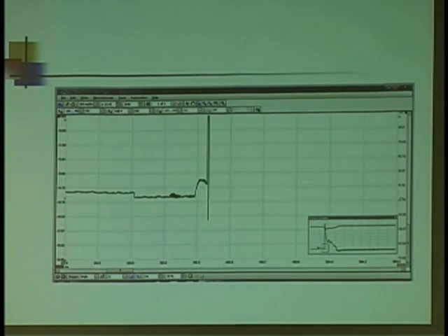When you first turn the key, I just turned to start. That's the solenoid closing. That's the current now passing through the contacts. Do you think if I saw that looking like a mountain range instead of a fairly smooth peak, there might be an issue with the starter? Okay, maybe that starter works today, doesn't work tomorrow.